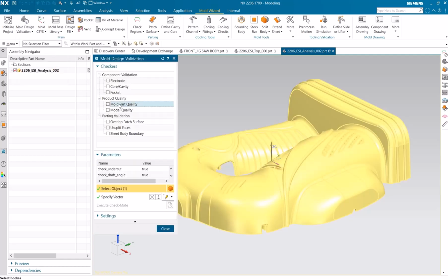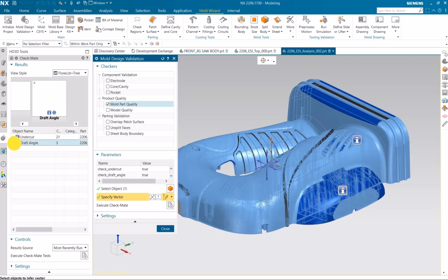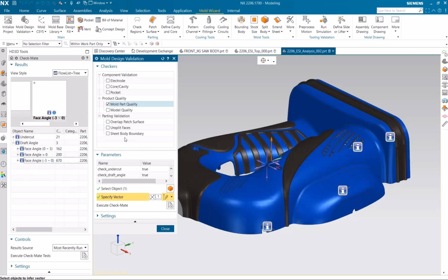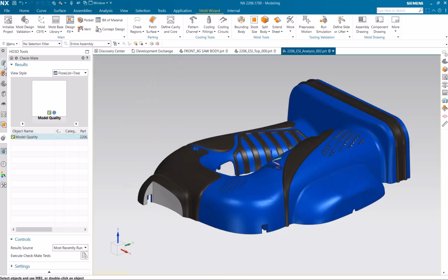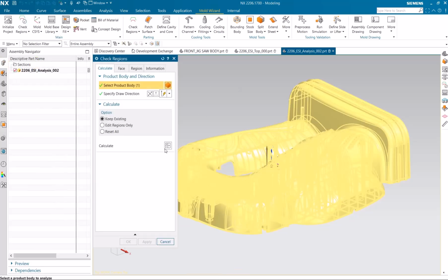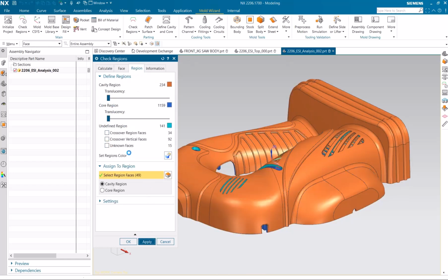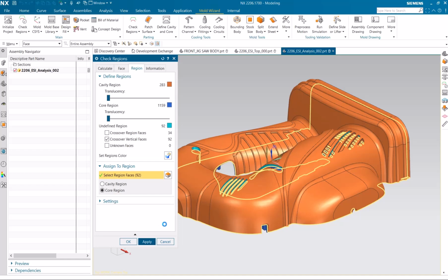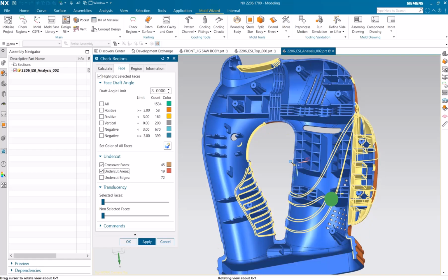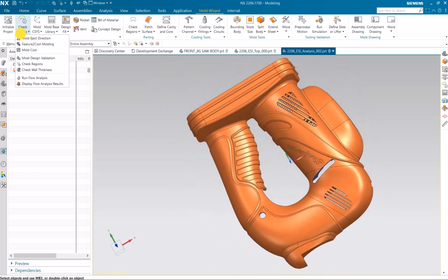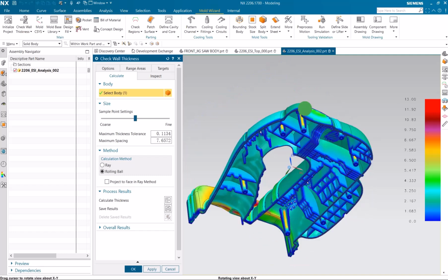The mold design process always starts with the following question: can this part be successfully molded? NX Mold Wizard's molded part validation tools analyze the part and automatically provide the designer with information about draft angles, undercut areas, sharp corners, etc. On top of that, it will provide the designer with an easy visual check of core and cavity side that doesn't require any special analysis or knowledge of mold design.